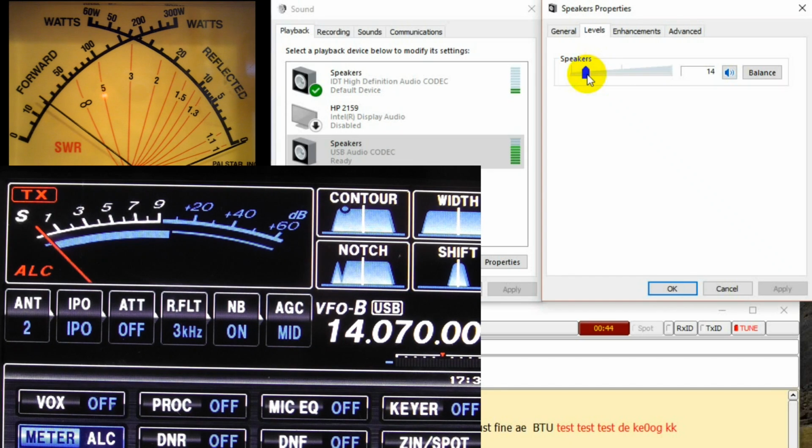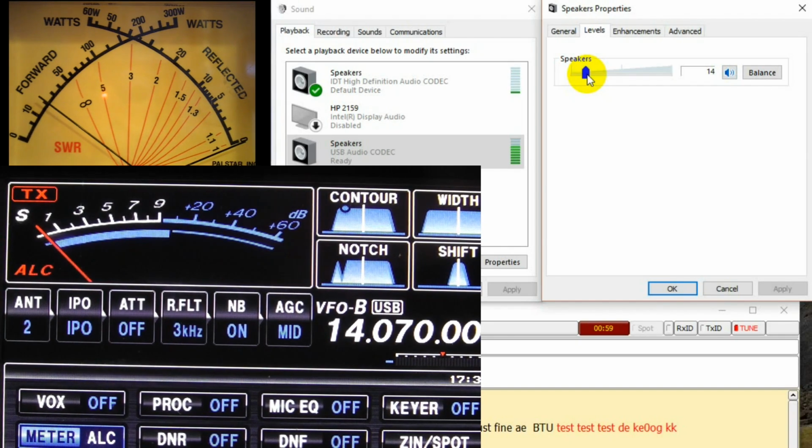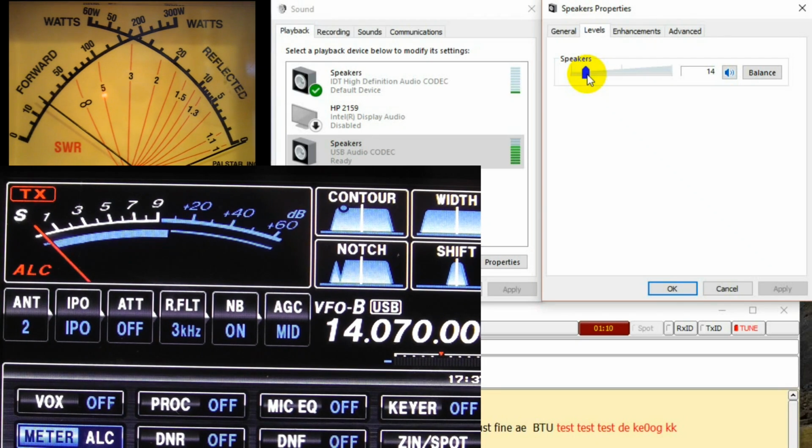Also, adjust your power out so that it's much less than the normal output. For example, if you have a 100-watt rig, you want to set the power out for about 25 to 35 watts max. That keeps the RF circuits very linear, and it keeps the rig from overheating because of the 100% duty cycle. Plus, you really don't need much power for PSK31 anyway.